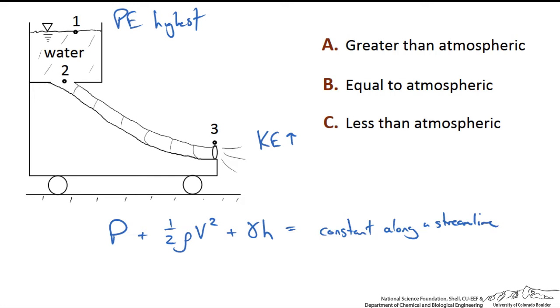The result is 3 components that could be related to the energy. These are actually energy per volume. We have what looks like potential energy, a kinetic energy term, and what we're going to call a flow energy term for this pressure. So thus the flow energy, or pressure, is related to the kinetic energy and potential energy.